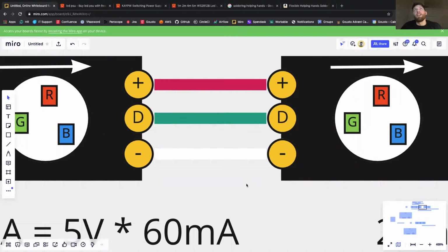That will help. And you will want to tin the pads before you attempt to adhere any wires onto them. So this means getting some solder melted down onto the pads before you attempt to put the wire on.